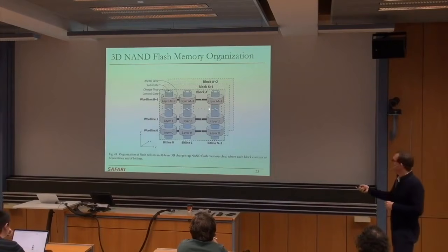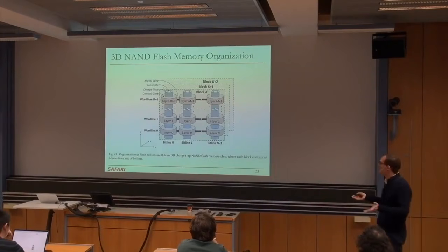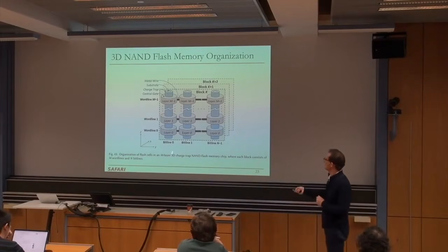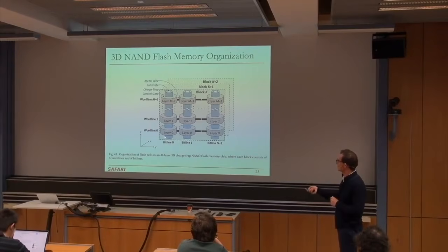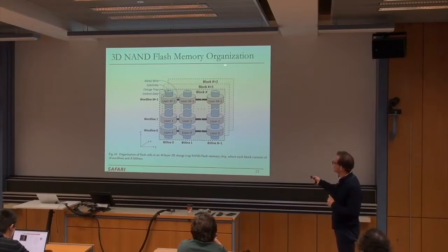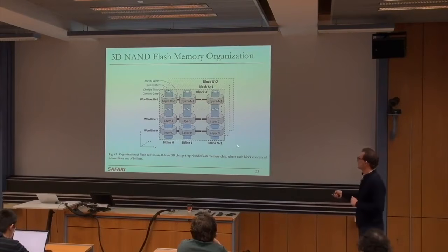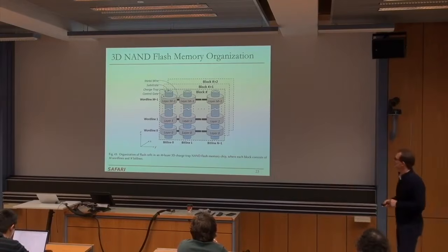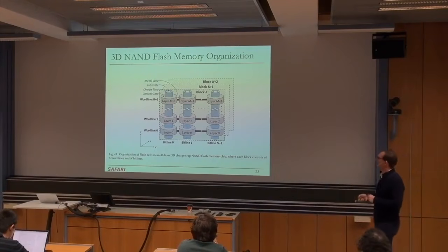This is nothing different from any memory that we examined, except it's three-dimensional, right? This is the three-dimensional bit line. It goes across, and this is the word line that cuts the bit line. And your blocks look like this now. Your blocks are essentially three-dimensional, if you will. And this is the other block, and this is the other block, dot, dot, dot, right? And you have the sense amplifiers at the bottom. Make sense? Okay. Add another layer, of course, that's a sense amplifier layer.